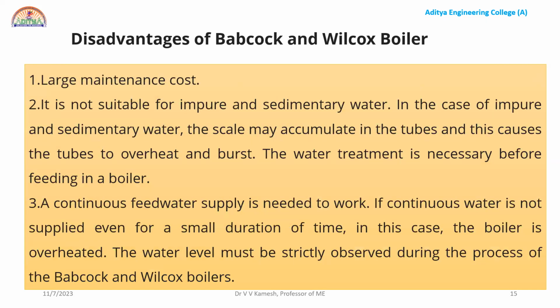And obviously there will be some limitations or disadvantages. The large maintenance cost is one of the difficulties, and it is not suitable for impure and sedimentary water. In the discussion of your mud box and the blow-off cock, I told you when there are impurities in the water, definitely there will be scale formation, right? The scales will accumulate in the tubes and this causes the tubes to overheat and burst, and water treatment is necessary before feeding into the boiler. So there needs to be a separate plant, the feed water treatment plant.